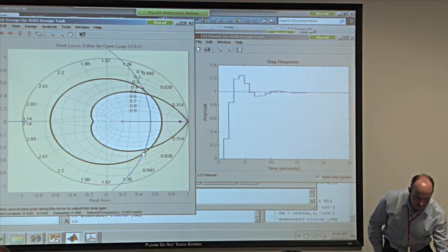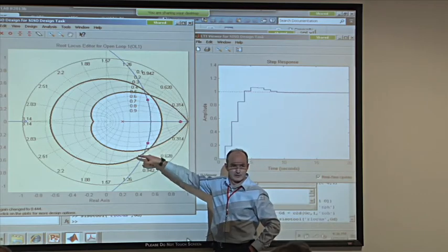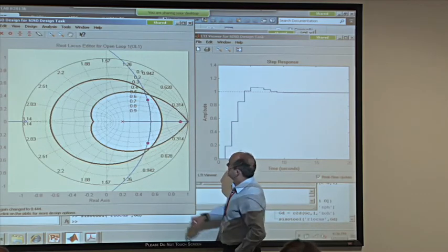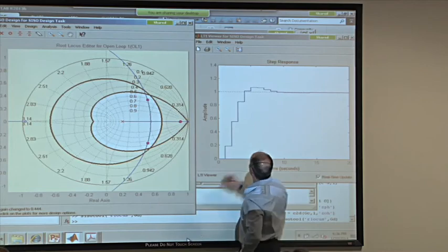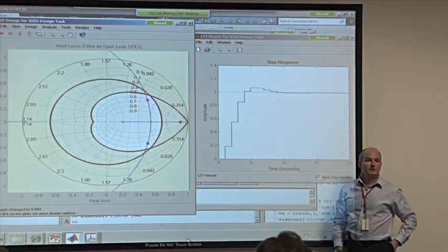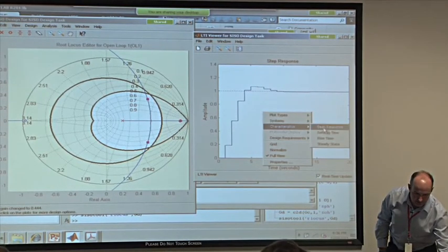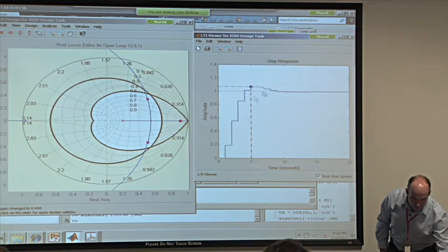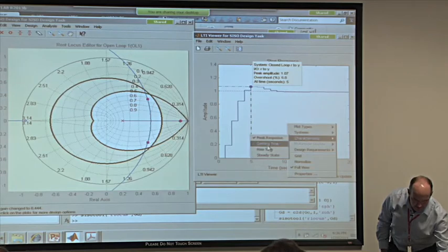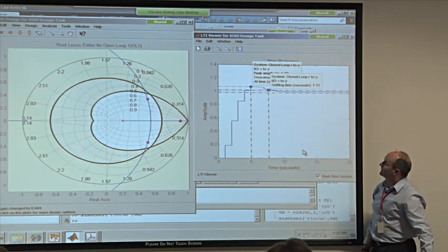And now we'll select, again, maybe just move it to about there, for example, because we've got a little bit of robustness margin in here. We don't want it right on the border. We'll pull it in a little bit. Well, we can see now we're meeting the 16% overshoot rule. I'd believe that. And the settling time to within 10 seconds, we're good too. Okay, we can measure these things if we want to on this response. Peak response is only 6.8%, and then the settling time 7.71 seconds. It's rather good, isn't it?